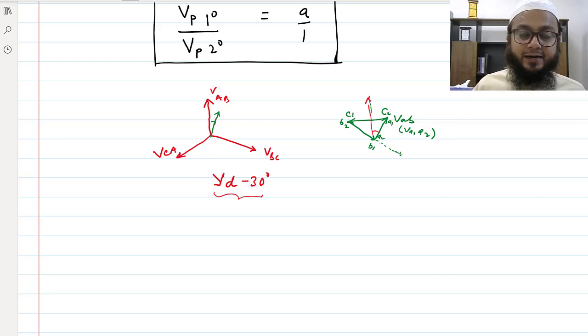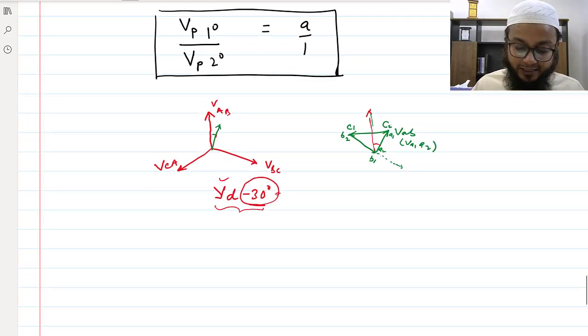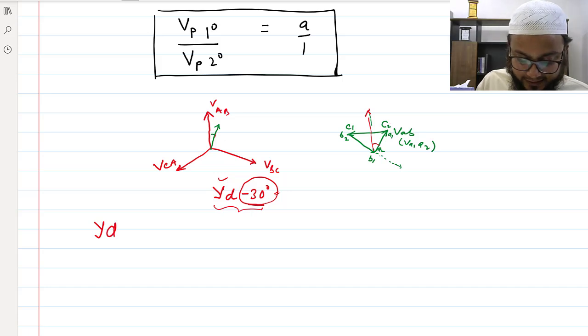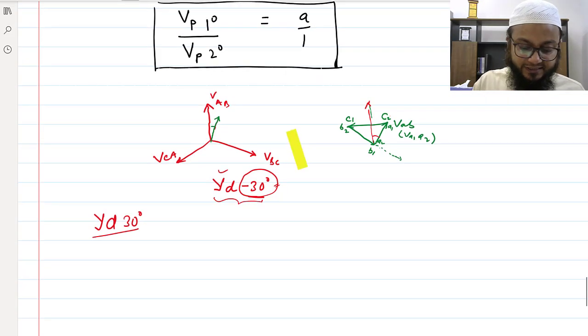So actually this is needed. Let's say you are connecting transformers in parallel, like if you are connecting two transformers, why is this important? You will know what would be the phasor difference between the primary side and the secondary side at the terminals. So you can easily use it for parallel operation of the transformers. Two transformers, if you want to parallel them, should be from the same group as well. So the third value which I am giving decides the grouping of this transformer. Similarly, you can try for YD30 as well. So even this connection is also possible.